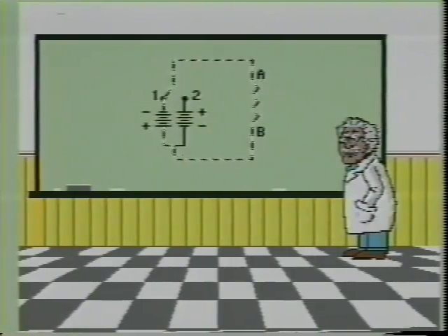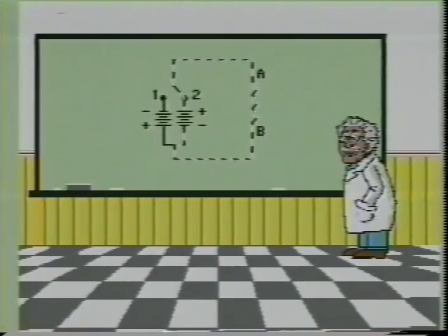When the switch is in position 1, the electrons will flow from the negative side of the battery through the switch and into the resistor at point A. Next, the current will flow through the resistor to point B and then return to the positive side of the battery. When the switch is thrown from position 1 to position 2, the current will flow from the negative side of the battery into the resistor at point B, through the resistor to point A, then through the switch and back to the positive side of the battery.